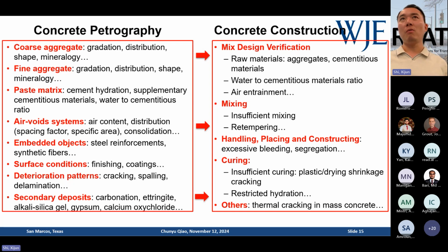The most well-known one everybody knows is concrete carbonation. So the carbonation depth, as a petrographer, you have to pay a lot of attention to it because that relates to corrosion. And also we look at ettringite. Ettringite can be a problem if we're talking about delayed ettringite formation, or it can be an indicator for high moisture level, as in any wet structures or structures in contact with soil or water.